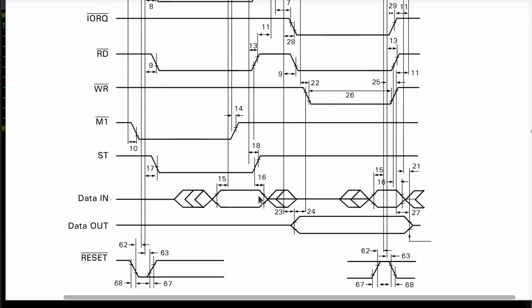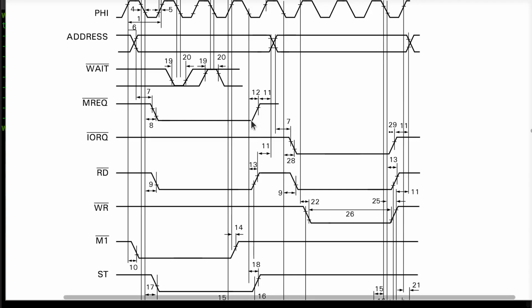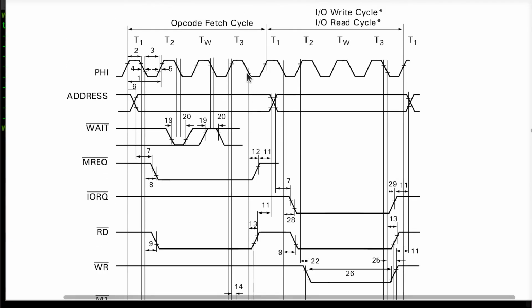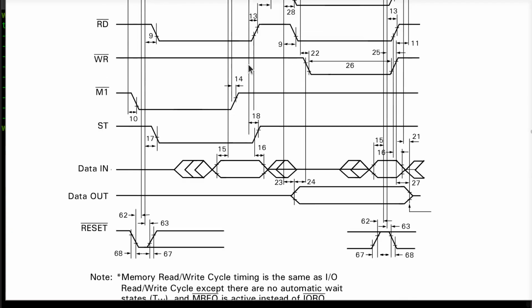The hold time is what? We'll see in the design that I'll keep the data on there until this rising edge goes out, and the sample that the CPU uses is on the falling edge of T3, and these are all 25 nano worst case after T3 anyway, which means it's at least 0 or if not more. So as long as I'm on there that long, we're good.